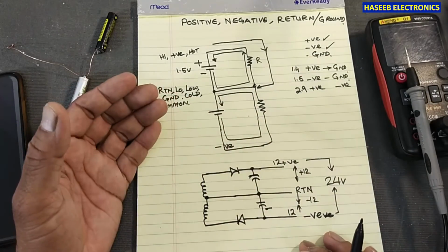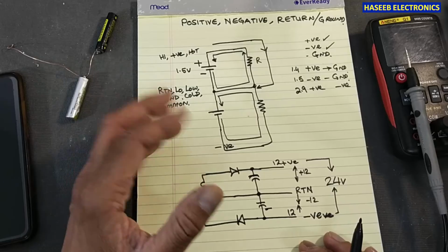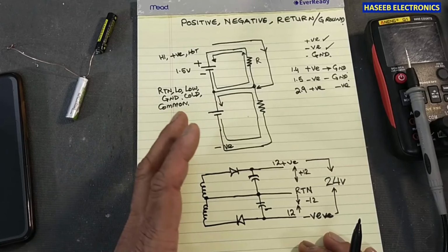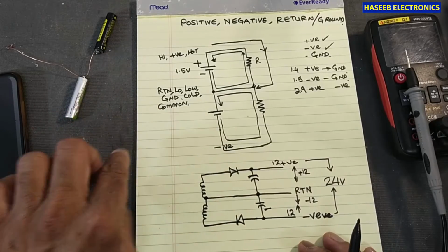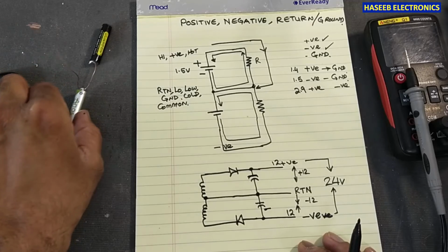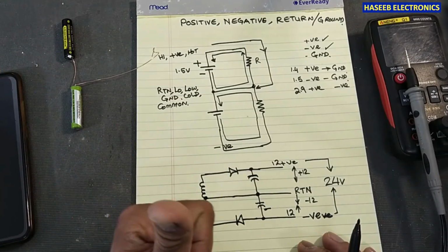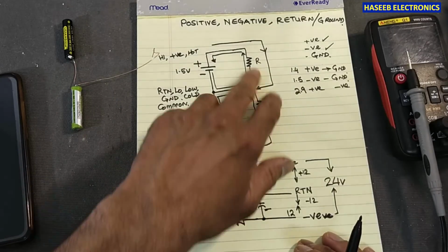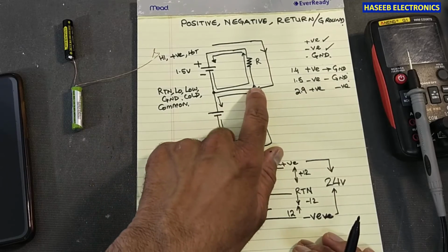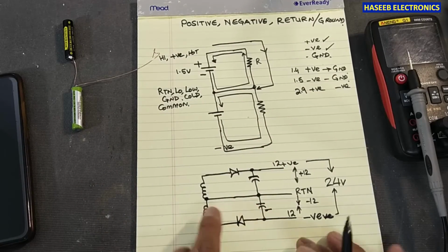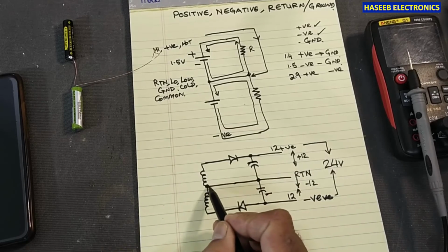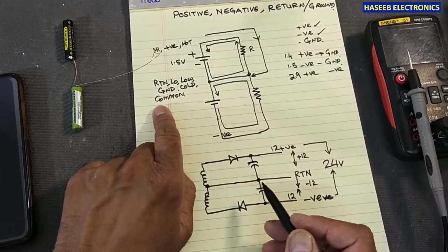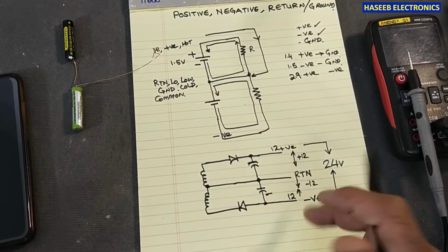In an electrical circuit there is a safety ground that is connected to the earthing ground. Earthing ground and chassis ground are for safety, connected to the earthing terminal of the ground potential and the earthing terminal to the transformer in our utility power supply. But in closed electrical circuits, the center point, the common node here, is called the return line, or low side, or ground, cold, common. So this terminal is our return path.